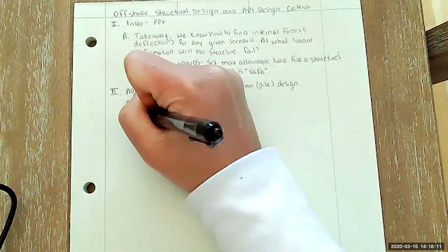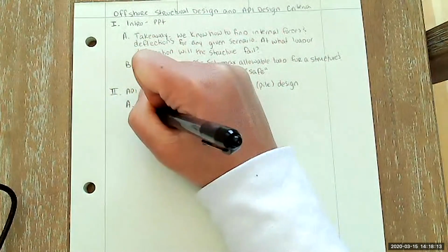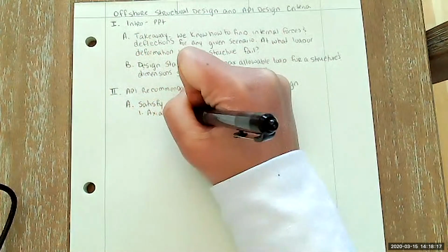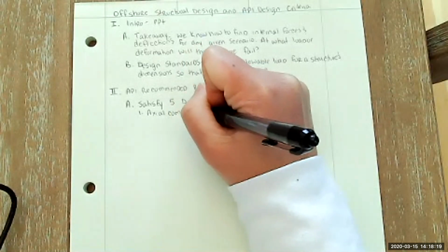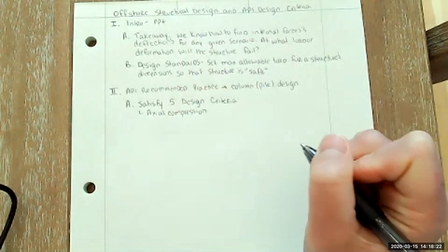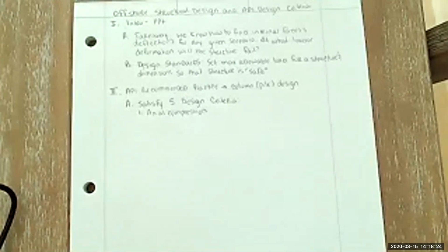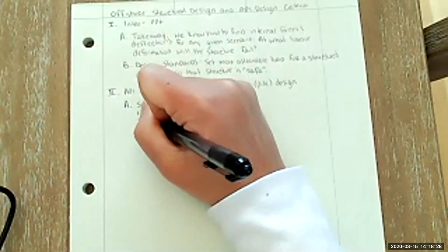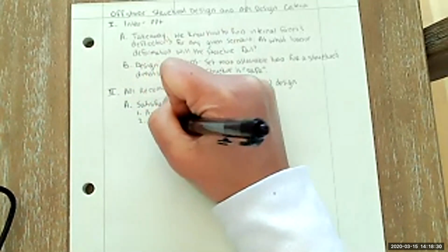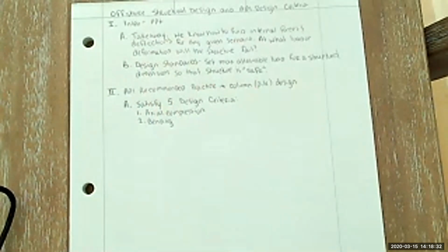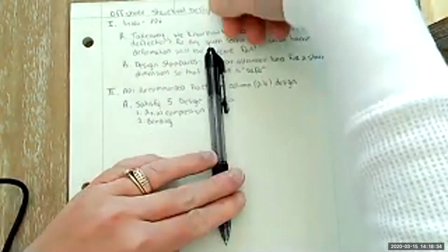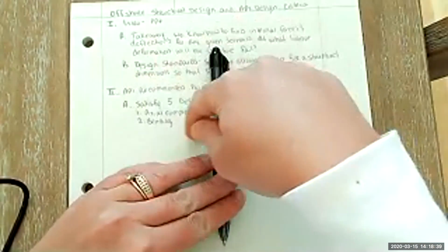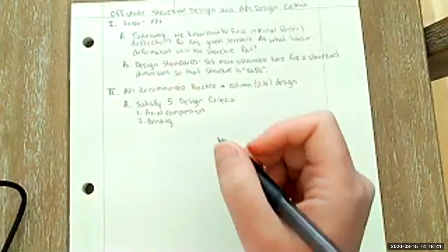And those 5 criteria that we have to satisfy are axial compression, to prevent local and global buckling, bending. So this would be due to a transverse loaded moment. So if this is my pile, we've got vertical loads coming here. Transverse loads would be something coming this way, maybe like a wave or a wind current.